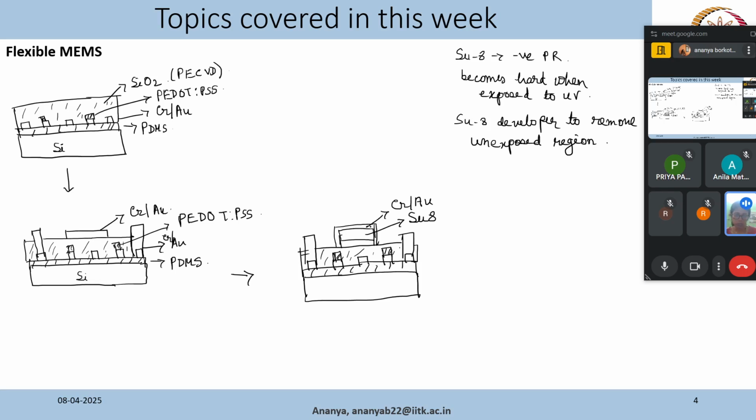Now we have this electrode to measure some electrical properties, and we have this contact pads and then this piezoresistive sensor to measure mechanical properties, and we will remove this silicon layer, silicon wafer, to make it a flexible substrate and flexible design, so that we can measure mechanical and electrical properties together. So our final device, final sensor will be PDMS.